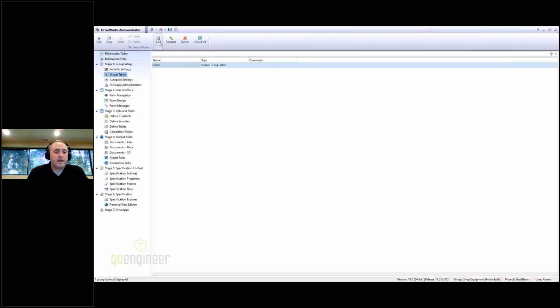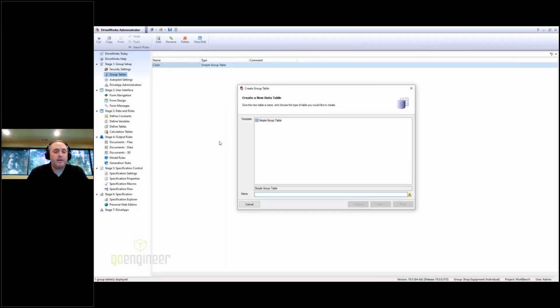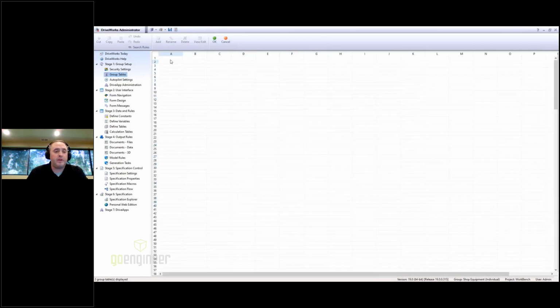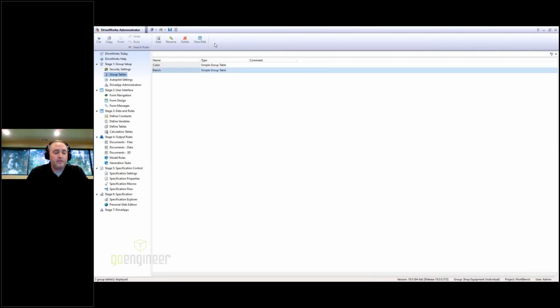So now that we have that captured in SolidWorks, back over here on the DriveWorks side, I'm going to add another table to make a choice between my 2 types, standard and heavy duty. Now the benefit of doing this as a table would be if another option ever came in, I just have to come and add a row. It takes me a couple of seconds and I'm off and on my way again onto other projects. So let's get our rating of heavy and standard in here. And then I'm going to cheat and copy and paste the profile names so that I don't mistype those, because those are critical. There we go. We have the 2 library feature profile names in our table.